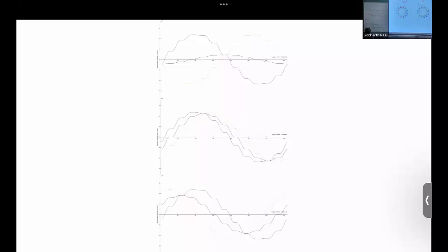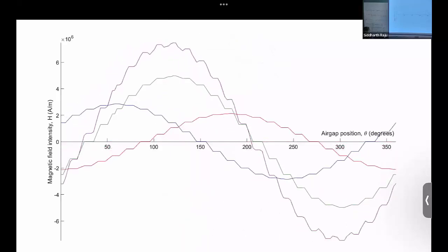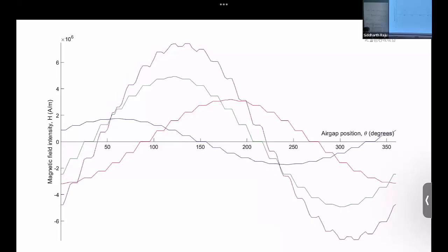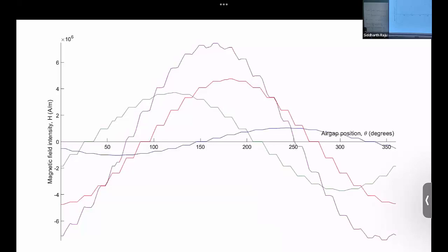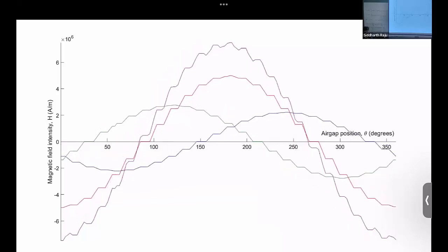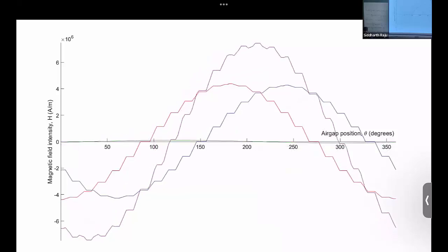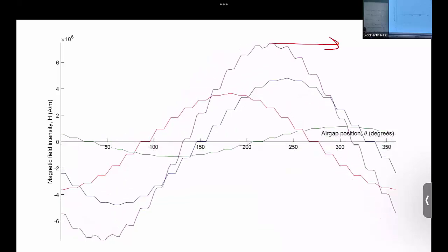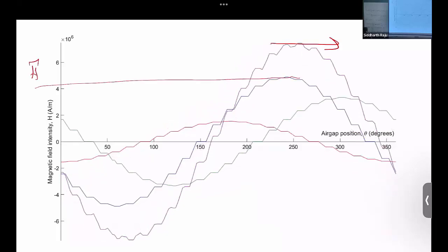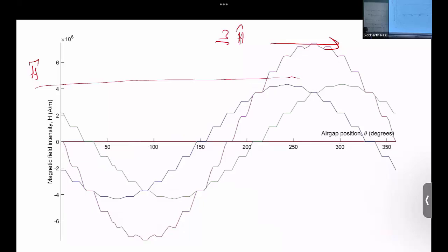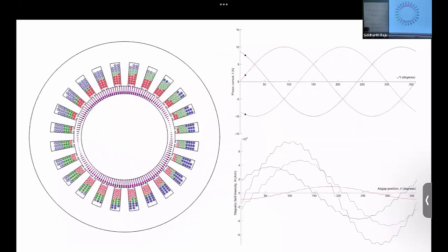Okay, right? And then here's basically when you have all of these three sinusoidally phase shifted currents going into windings that are physically phase shifted by 120 degrees, you end up with this net wave which travels in just one direction, while each of the individual waves of the H field vary up and down, but the net wave is always going to be going in one direction. So if the peak of any one single value is, let's say, H peak, then the net would be H peak times 3 by 2, right?